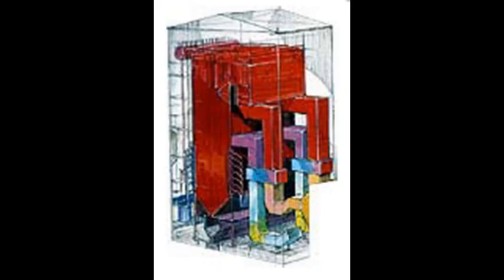In boilers, we provide this oxygen through air, and as I have already mentioned, some air is used as primary air, which is utilized for conveyance of coal up to the furnace, and some air is utilized for completion of combustion, which is called secondary air.